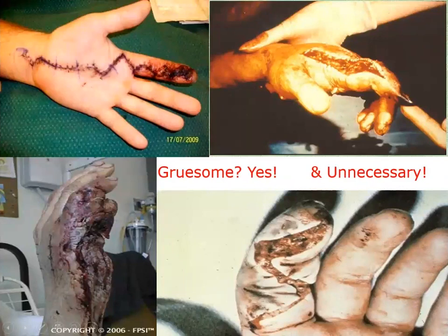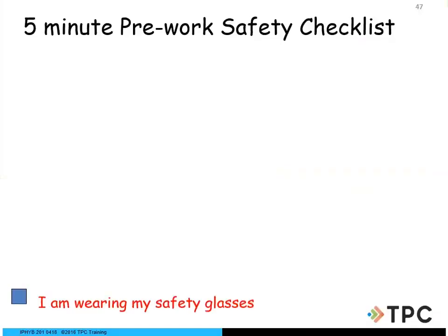Most of them are hands, because we're trying to work on something, right? And take this valve off and take this fitting apart. We did not depressurize the system, and then you have that hydraulic injection going into your hands. So that's what mostly occurs. That's why you see a lot of hand accidents relative to hydraulic injection instead of your feet and legs.